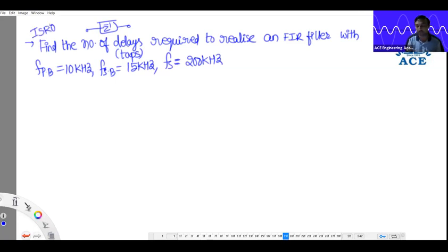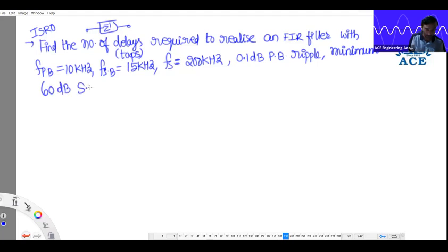Find the number of delays required to realize an FIR filter with passband frequency 10K, stop band 15K, sampling rate 200K, 0.1 dB passband ripple, minimum 60 dB stop band attenuation. Number of delays means he is asking for order, sir.